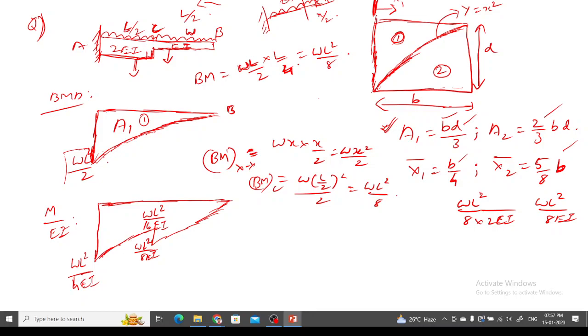See, from A to C, I'm not calculating from the left hand side or from the right hand side. Here, I am taking the cantilever beam only, without any change in the moment of inertia or in the Young's modulus value. This bending moment equation is valid for the whole beam, right? Yes, sir. Means we can use it from any side. Yeah, any side. So here I have taken from the right hand side alone. So the x value I should put from this side.